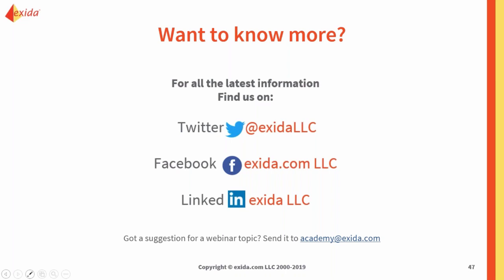This is kind of a follow-up on that 1 out of 1 everything for a SIL 3, talking about could a final element be classified SIL 3 without a partial stroke diagnostic test? And I'm assuming you're still talking about a 1 out of 1 final element. And it really depends on a lot of variables that go into that equation. That's not something that I would just feel comfortable saying yes or no without getting more information. However, if we're still talking about that 1 out of 1 everything for SIL 3, that architectural constraints is going to kind of veto that.